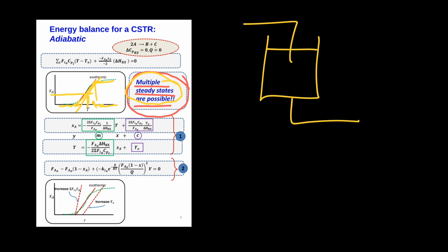So what we must note is, if I now use fsolve, I give it an initial guess. If I guess initially my X is 0.5, and I guess a temperature, because I know it's exothermic, just higher than my inlet temperature, it will definitely converge to that point. If I guess higher values, it can converge to that point. If I guess a lower value, depending on the solution procedure it uses, it can find each of these operating points. So what is important to note is that this is not just a mathematical glitch, and that one is going to be the operating point where you will definitely operate.